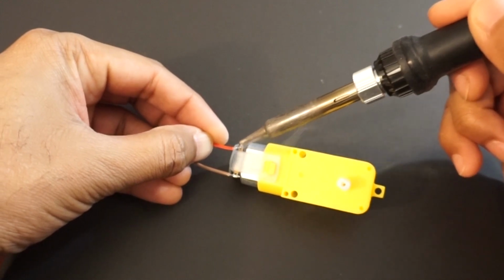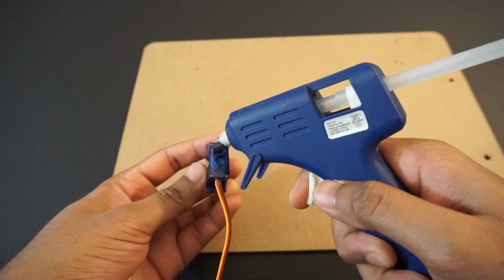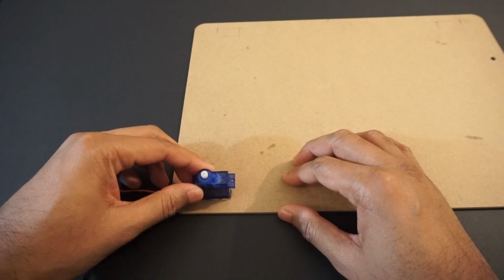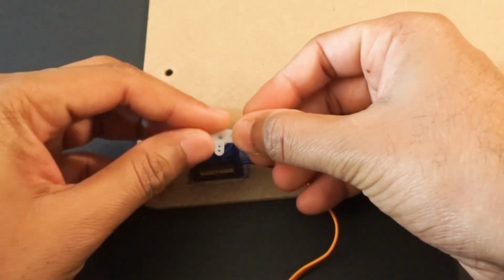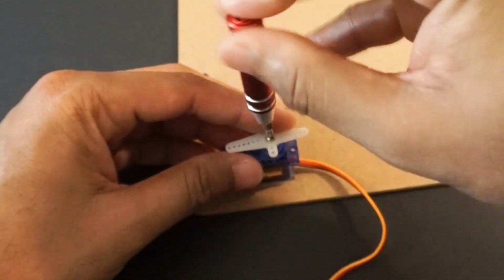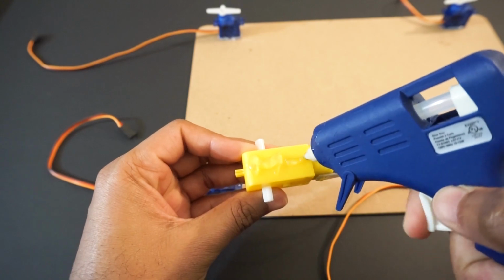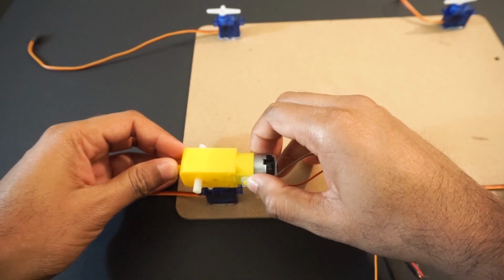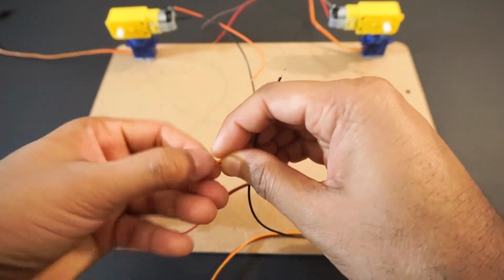First, let's solder wires to the gear motors. Mount all 4 motors on the car chassis using a glue gun. Fix the plastic connectors to all servo motors and screw them properly. Attach the DC gear motors to the servos now. Make sure these are aligned properly. Join red to red and black to black wires of the DC motors on each side.